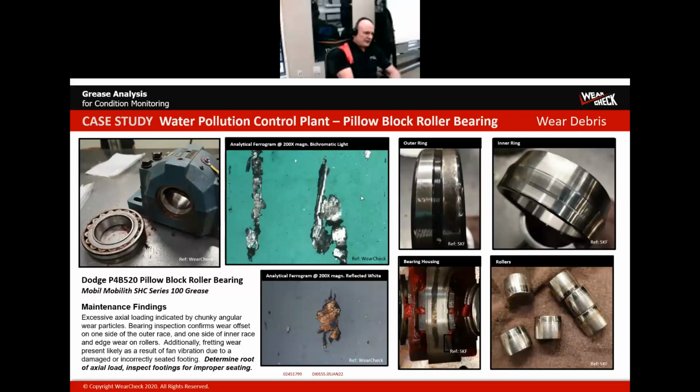The customer was kind of surprised because they had done a bearing failure analysis, and it turns out that this is what was occurring. There was a lot of wear occurring to the one side. I think it was the upper tapered bearing on one point was experiencing a lot of irregular axial load. It could be identified from the failure analysis on the bearing.